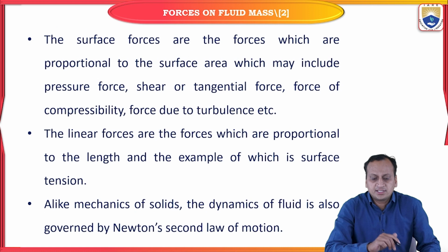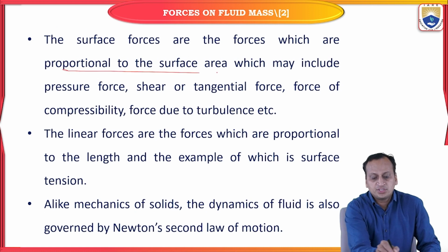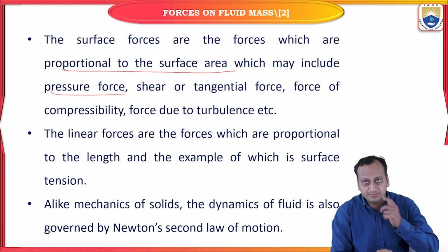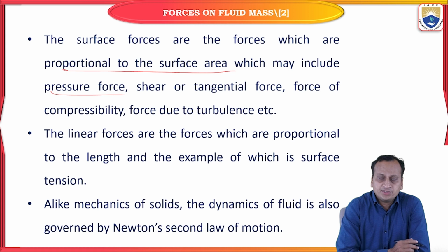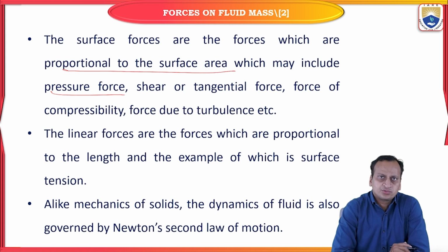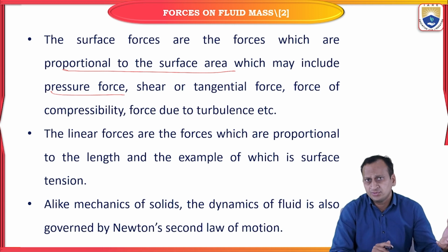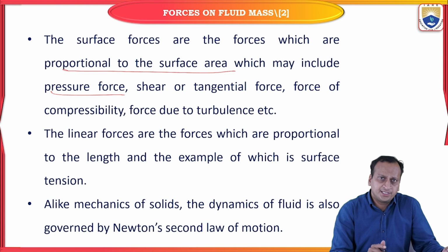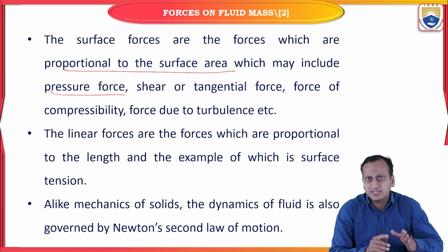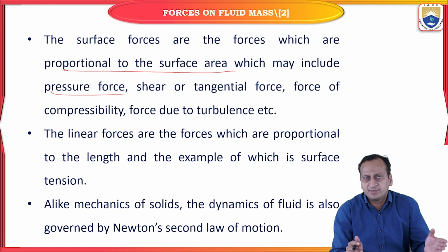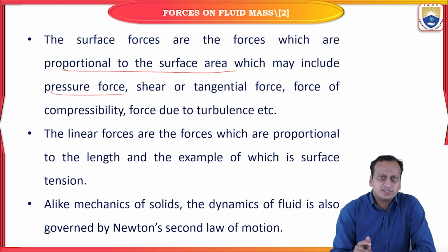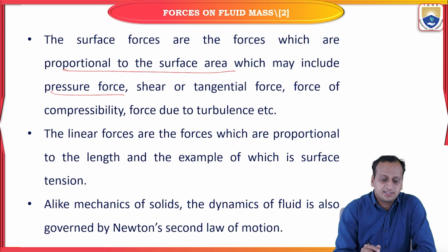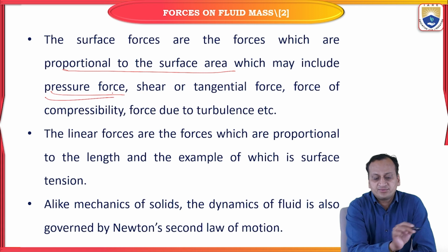Similarly, the surface forces are area forces which are proportional to the surface area, which includes the pressure force. The unit of pressure is Pascal, Newton per meter square, which indicates the area. The pressure force is developed due to the pressure gradient. Where there is a pressure difference, there will be a pressure force. Based on its unit also, you can understand that the force is due to pressure. So pressure force is one example of surface force.